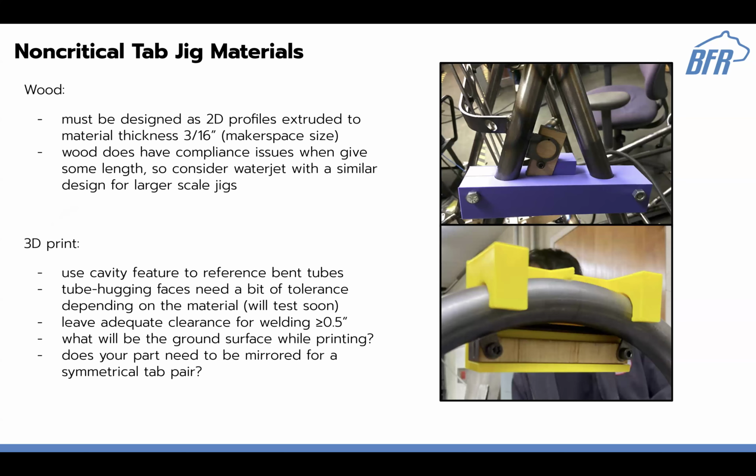So you might see that if you're printing a hole vertically, it might end up really oval, or the layers might mess with its circularity. If you're really worried about the fitment of your bolts, you can do a similar thing to what we do for water jetting, where you drill out the holes afterwards and undersize them a tiny bit, or you just change your print vector. The most critical holes should be in the 2D plane of your print bed.